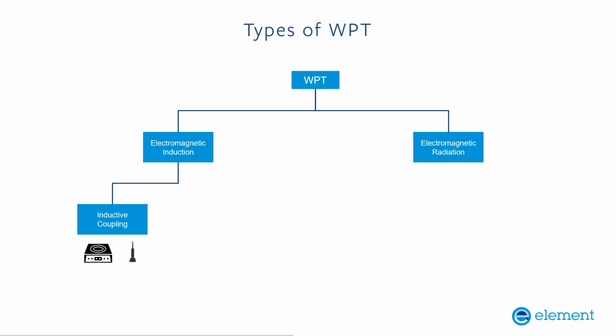The other side, and where we've seen many more use cases in recent years, is with regard to magnetic resonant induction. And this is where we basically resonate a coil, maybe offset the coil frequency slightly, but essentially we're at some higher frequency to get improved efficiency, and also resonating the coil to get maximum power transfer between the source and the load device.